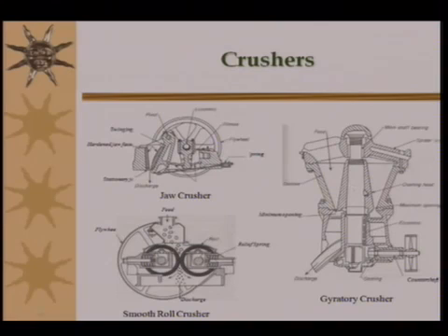These are the crushing heads, this one and this one. At a high speed these crushing heads revolve, and the material received in this feed area is crushed. The speed of these gyrations is about 125 to 425 gyrations per minute, and the maximum capacity of such machines is 400 tons per hour.